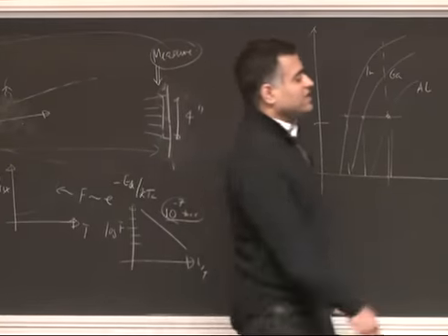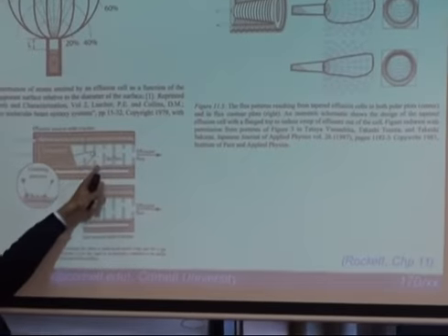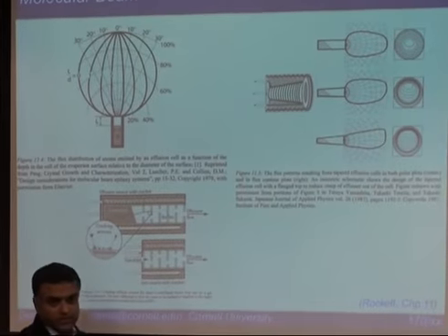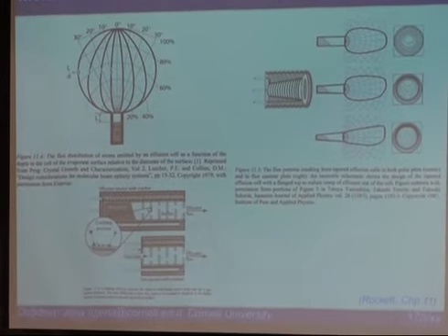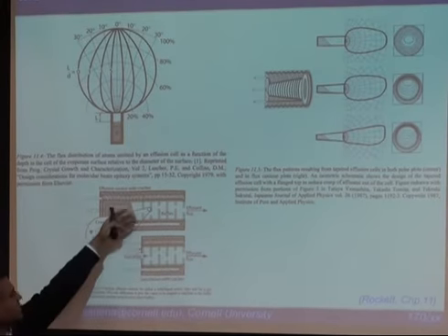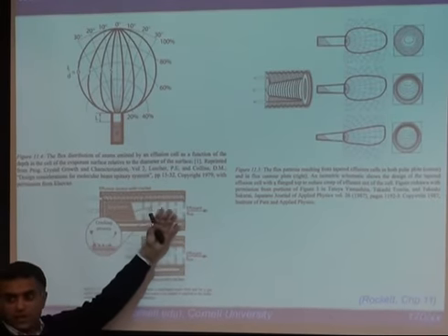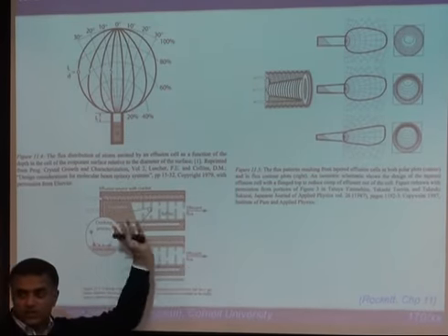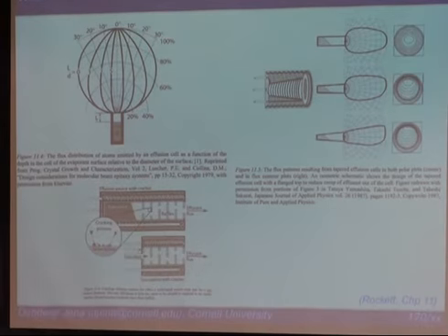So what you do is, again, a very simple technique. It's called a cracker cell. So essentially, all that you have done is you have introduced a much longer and circuitous path for the atom to go through here. There are some other tricks that are played. You heat these things and all that. But essentially, the goal is you just filter out the heavier elements, tetramers and all that, and you want only the lighter ones to get out here. So you make it a little harder for them. Effectively, you're filtering out the heavier parts, and they just stay within the crucible, and the rest can go. And lots of other tricks. So, for example, there are gas sources.